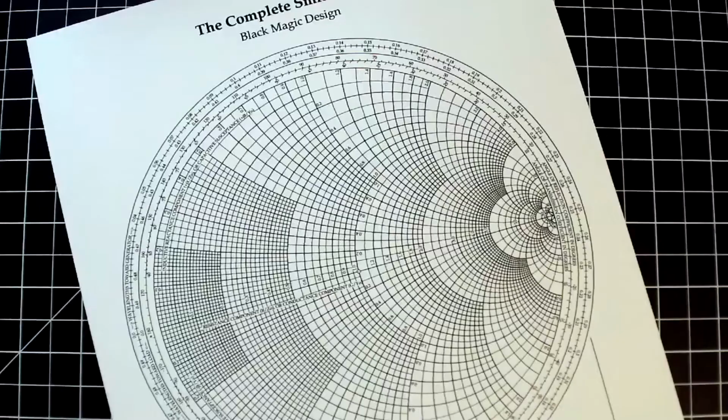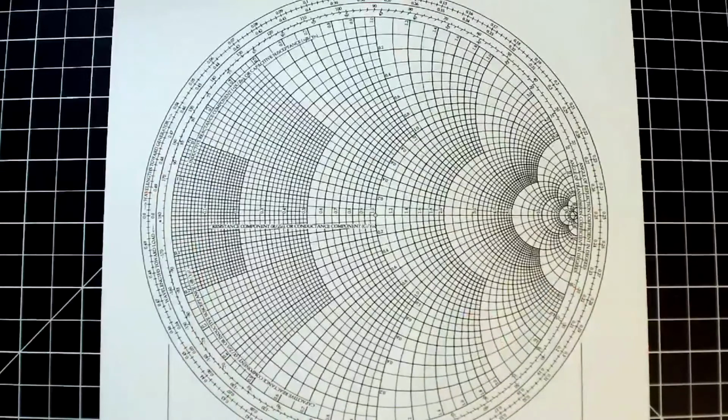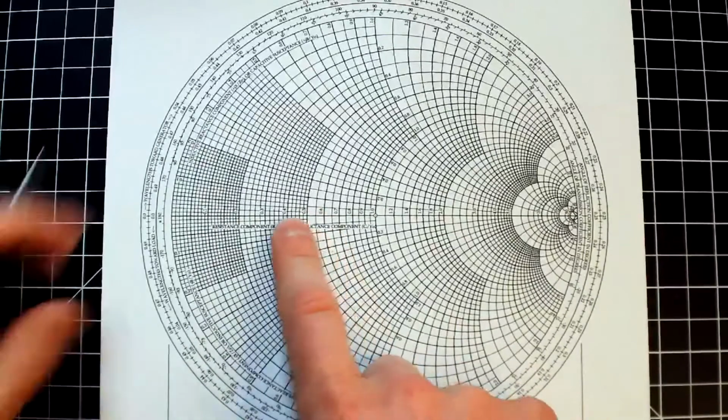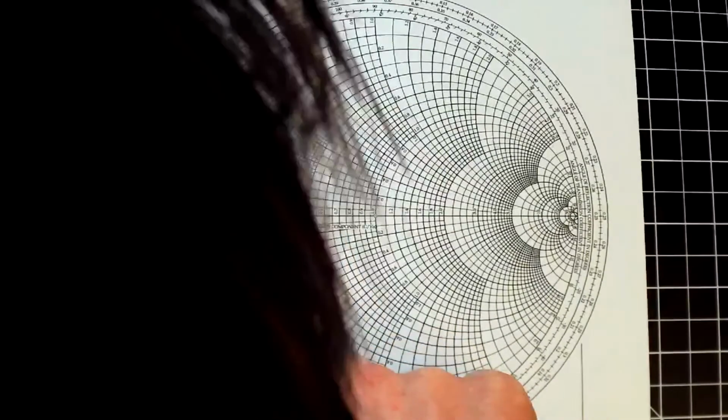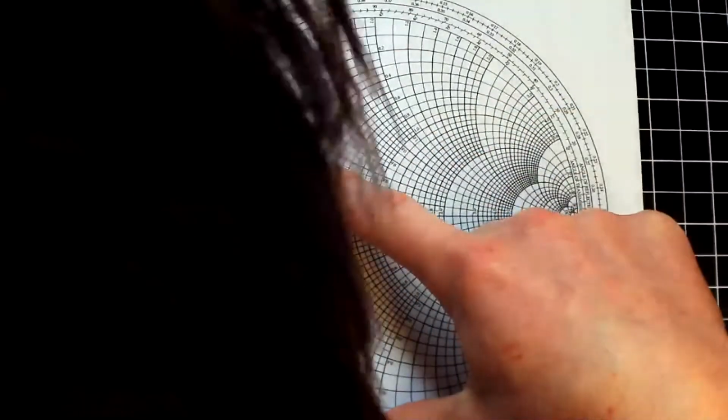So can you see this? There we go. So there's two ways to do this. One is you can just plot gamma directly, or when you plot the normalized load impedance, it was 0.33. So you read out here 0.33, and then it was plus 0.33 again, which brings us to about here. 0.33-ish, about there. So that took us there-ish, okay?